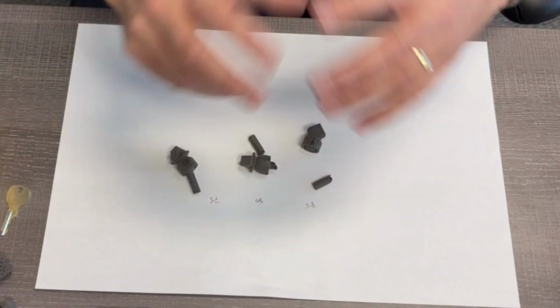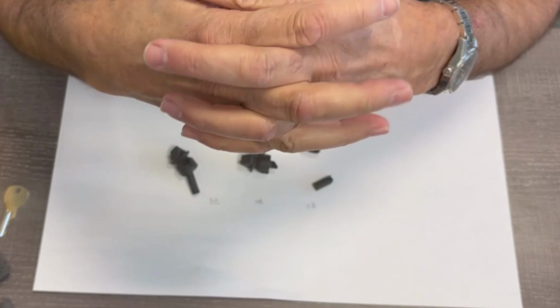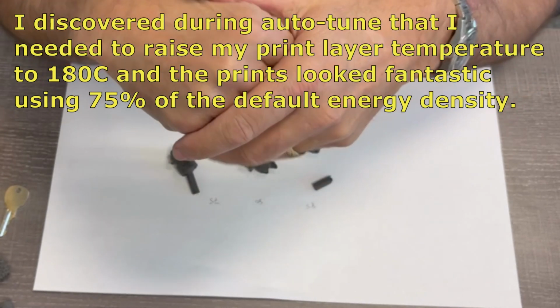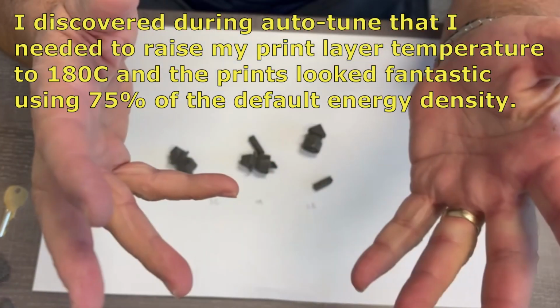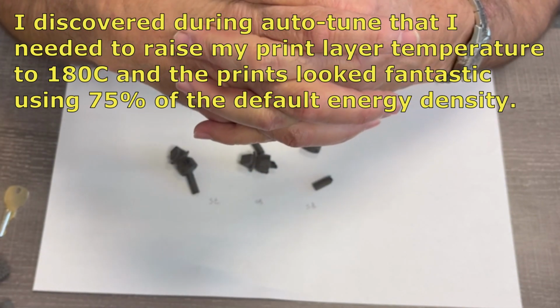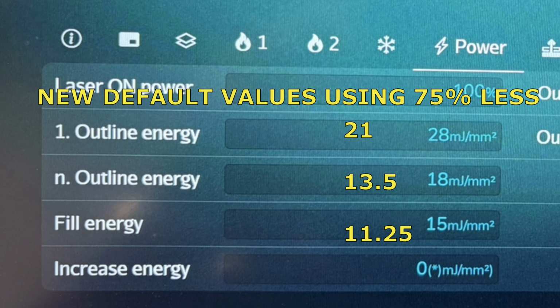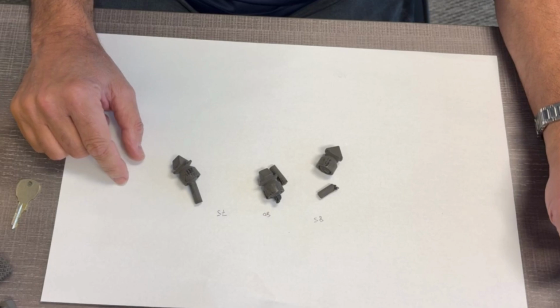But overall, in terms of settings for me, and it has to do with my print surface temperature being at 177, with these energy densities, if I run at 75, I'm running good parts, and I think that's where I'm going to go forward. I'm going to do some more prints, and if I find anything that tells me different, I'll let you all know. So as far as printers go, there's some room in the energy density, especially if you're having troubles with tolerances. Okay, well, that's it for this print setting, and stay tuned for the next one.